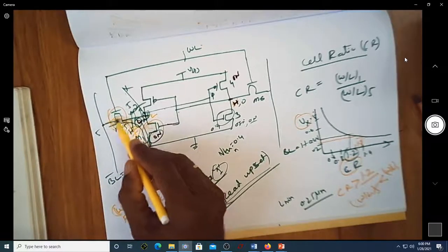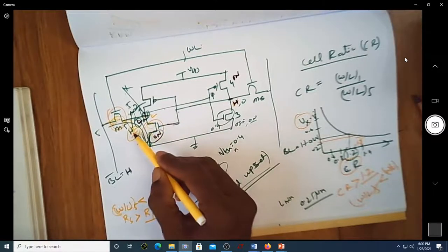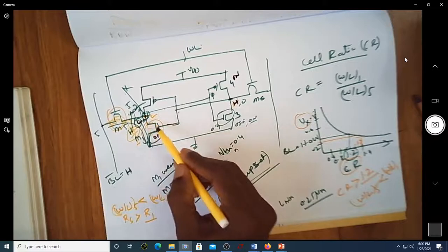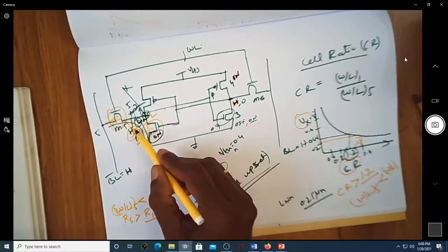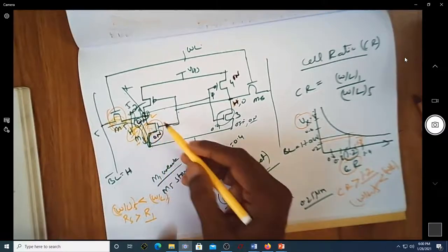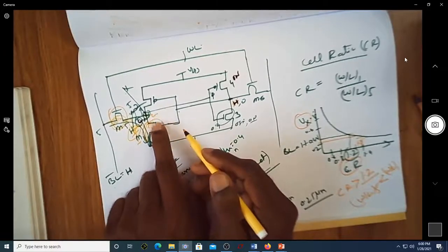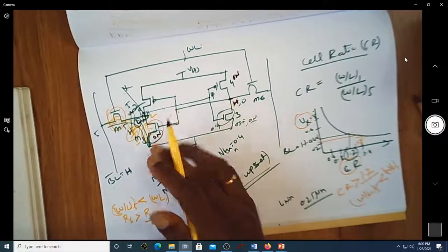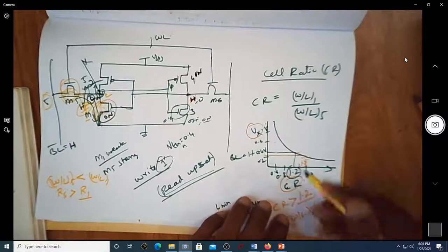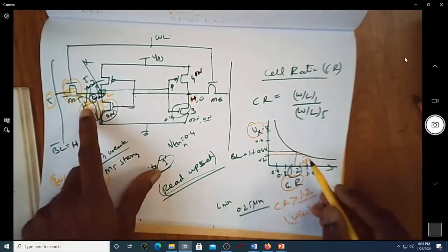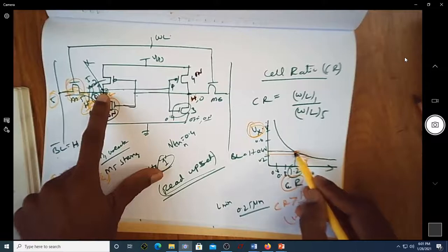Since the resistance value is more, it takes longer to charge the voltage, but as soon as the voltage tries to rise here, since the resistance offered by this is less, the same charge will be discharged very soon. So the low voltage you had earlier will be maintained even though you are turning on this transistor with 5 volt. Meaning, the voltage at this X point won't rise.